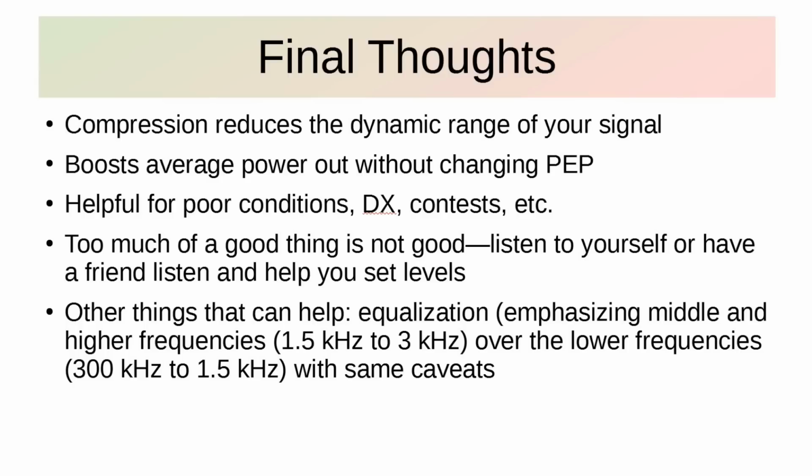Now, too much of a good thing is not good. Listen to yourself or have a friend listen and help you set the levels. I listened to myself by recording a little video, and you heard in there where it was rather loud. I think it was too much compression. I'm going to back off a little bit. You can go by the manual and do this, but you still have to listen. There's no substitute for the wetware between the ears.